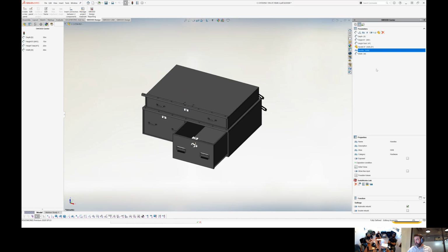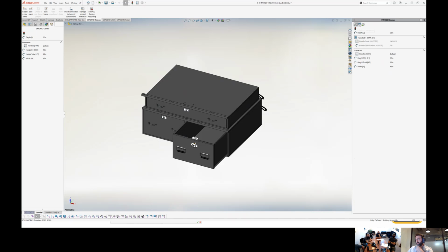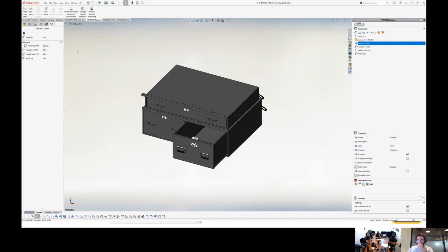So could I go into the configuration file and add 20 different lines and have 20 different configuration models created from them? I will have to go through each one the first time, but after, yeah. For instance, I have 80 models on the web, of which 50 are all 2 drawers of different heights. If I could make one model and then add 49 configurations driving your parameters, I could have my entire library in 2 hours.